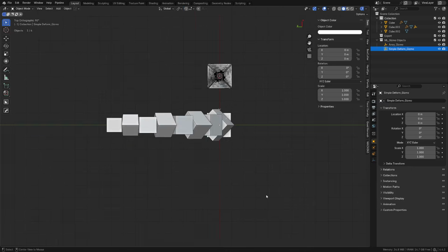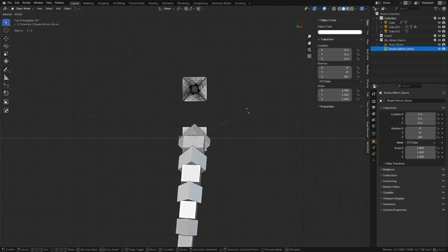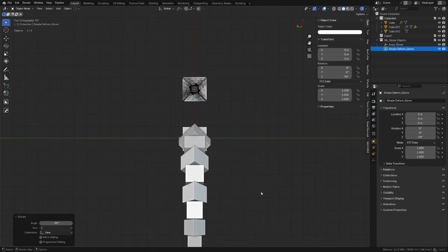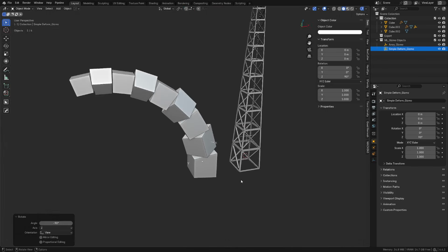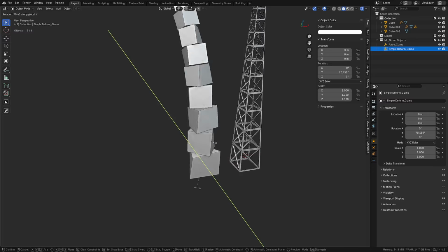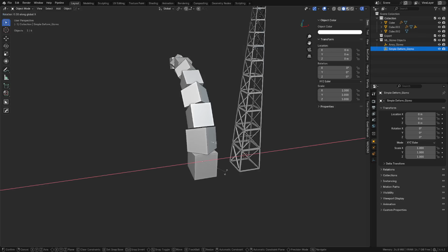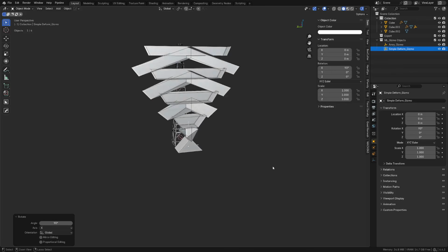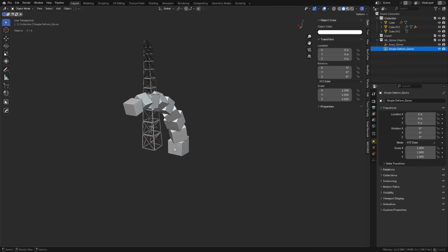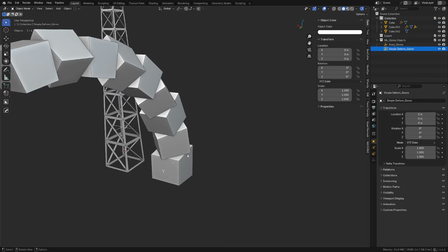So if you ever wanted to keyframe these kinds of things and animate them this way, I guess you could. But if you want to change the direction, perhaps you hit R and Z in that case, but sometimes R and X and Y. A lot of times RX 90 will usually fix the problems you're having with it, but you have to rotate them sometimes twice, right? It's usually an RY or RX or RZ 90. And then you might have to do another one, like another RXYZ 90 or 45 or whatever you need.